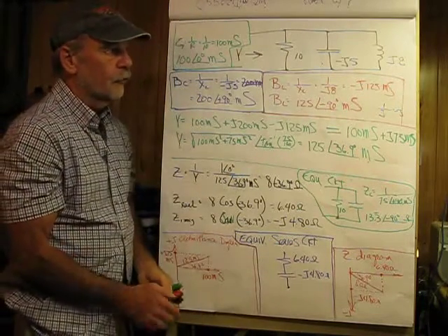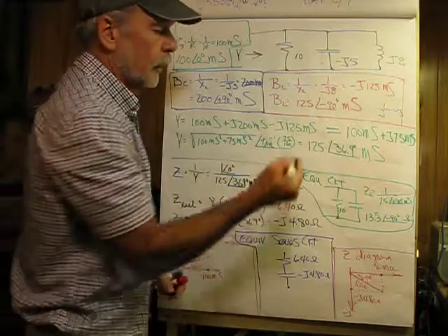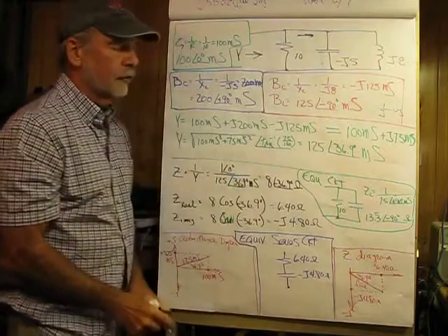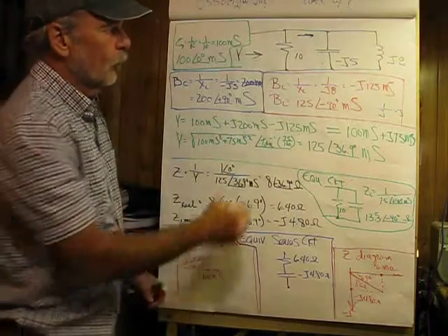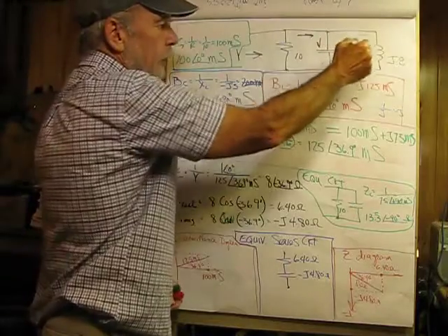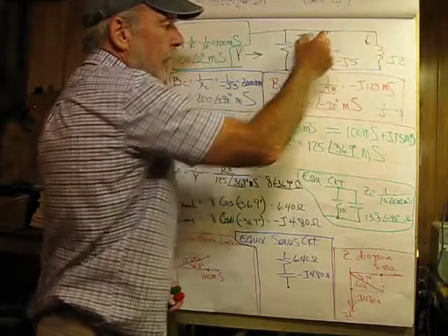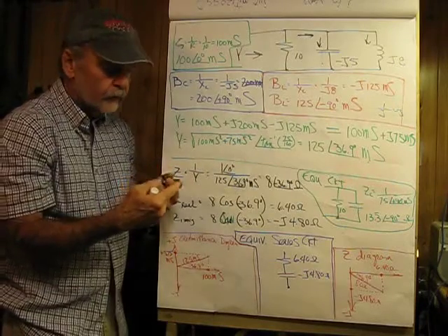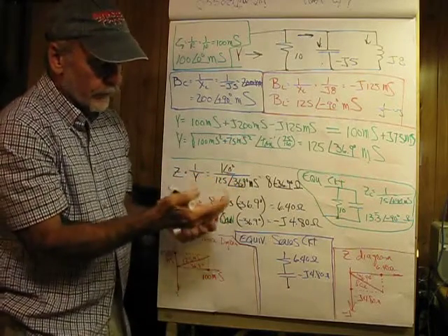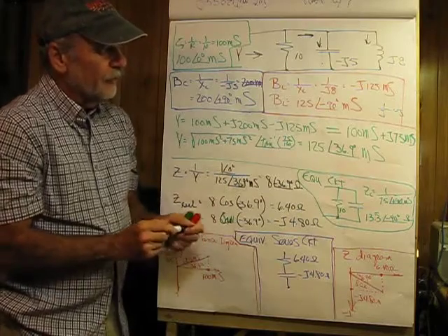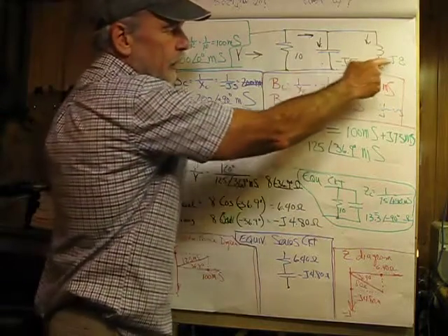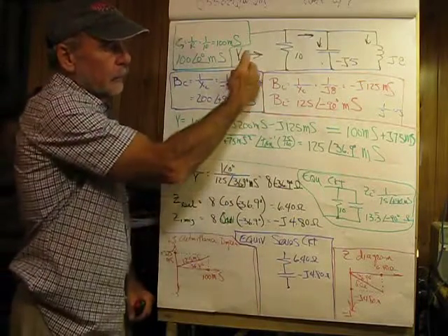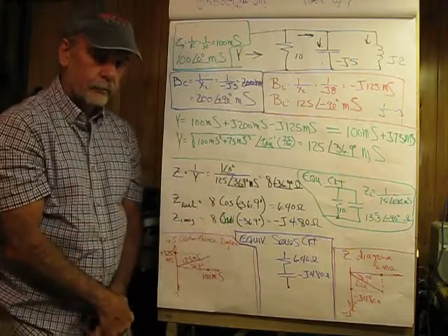So in the equivalent circuit, the actual current flowing into these two parts is significantly less than what we would have flowing in this part and in this part. And remember, algebraically, they subtract from each other. That's kind of a little bit abstract, but the fact is if we had these both being equal, they would completely cancel, and the impedance of the whole circuit would be 10 ohms.